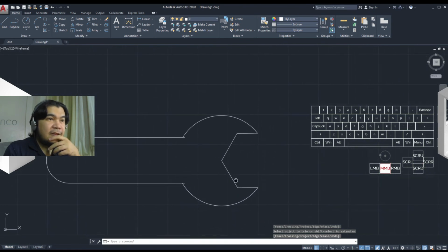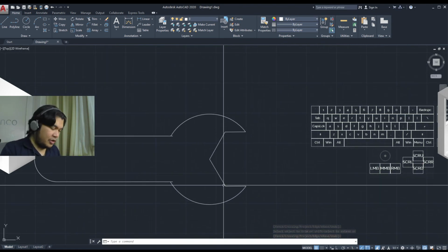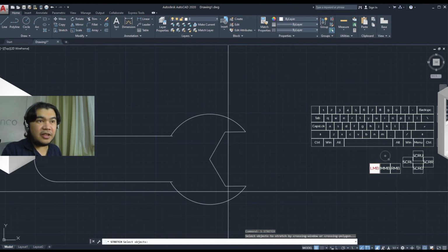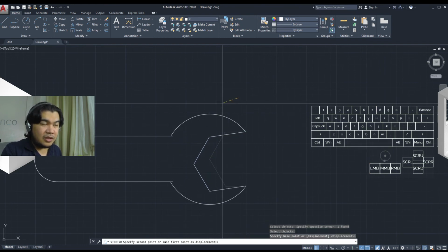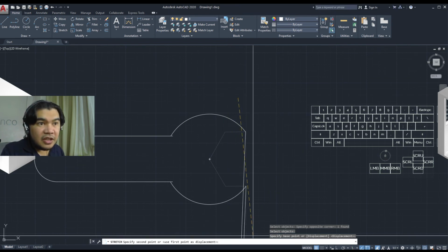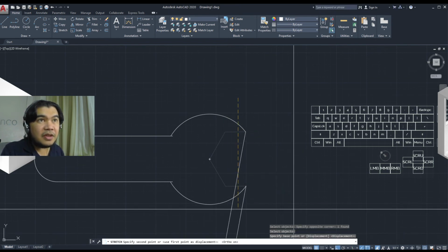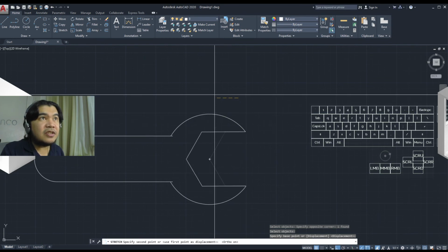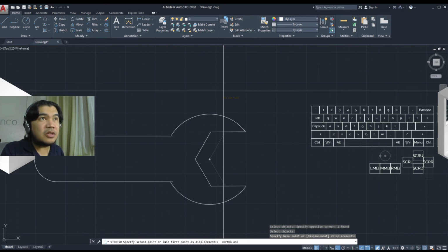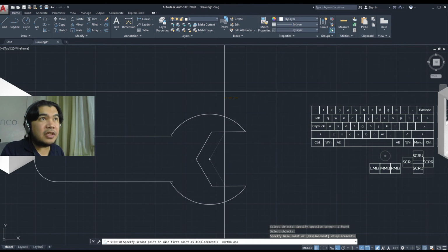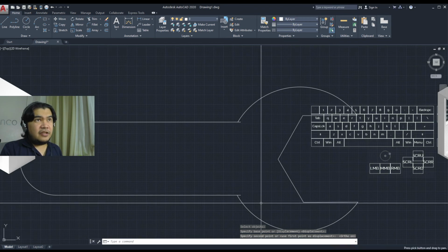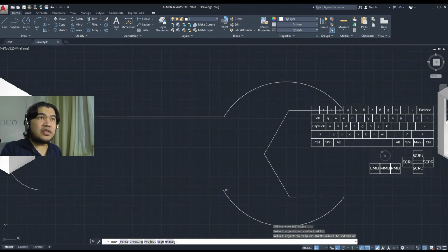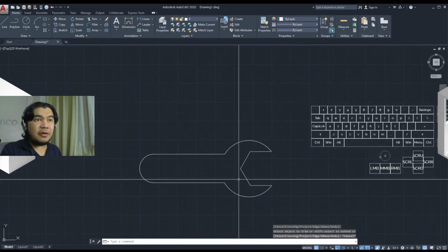And yeah, that could work, or we could just maybe refine it a little by using a stretch command on it. Again, use the orthographic setting. So we're locking it basically into an x-axis. And then, yeah, let's re-invoke the trim because there's some parts here that we don't want. And then there we have it.